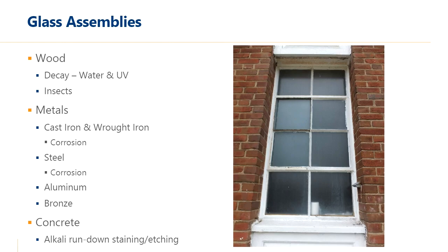This is another type of steel window, which is more of an industrial application. With ferrous metals, the most often condition will be related to corrosion, which is shown here, where it's forming on the muntins where coating and glazing putty is no longer intact. Corrosion is expansive and can result in metal to glass contact and pressure, along with a loss of metal material.